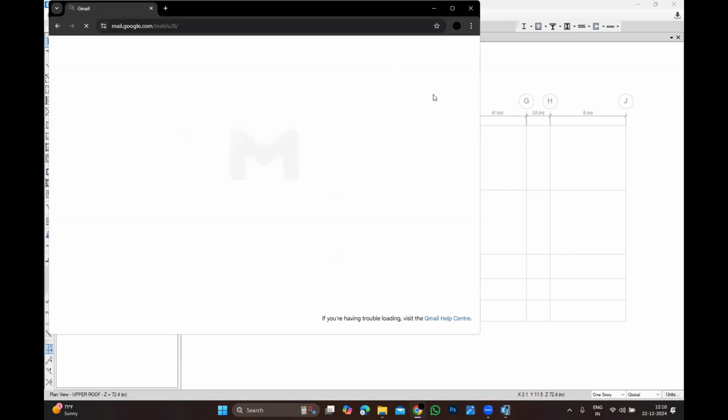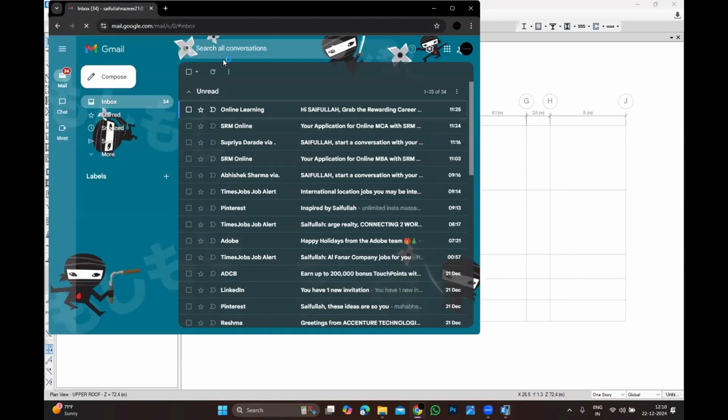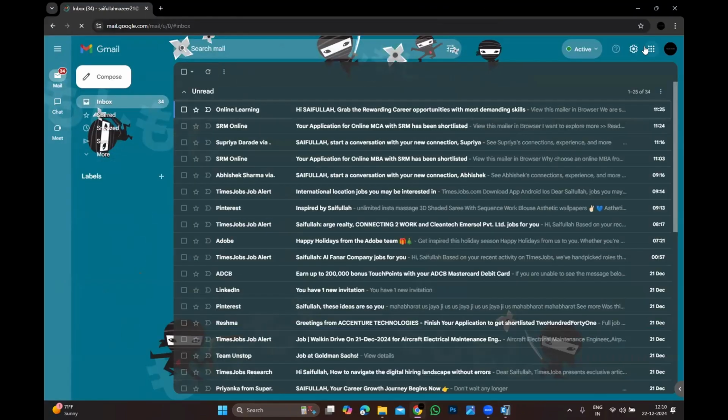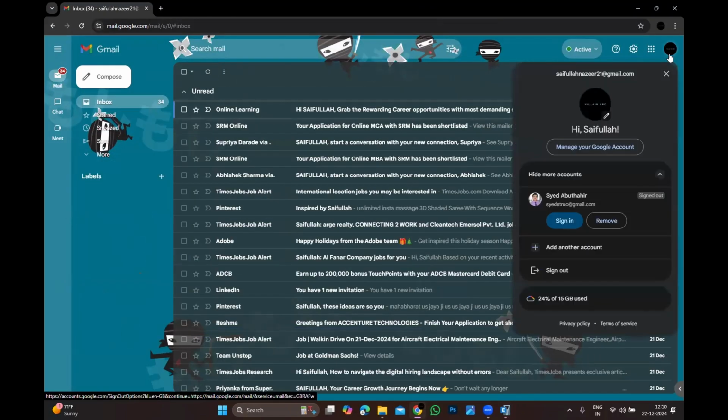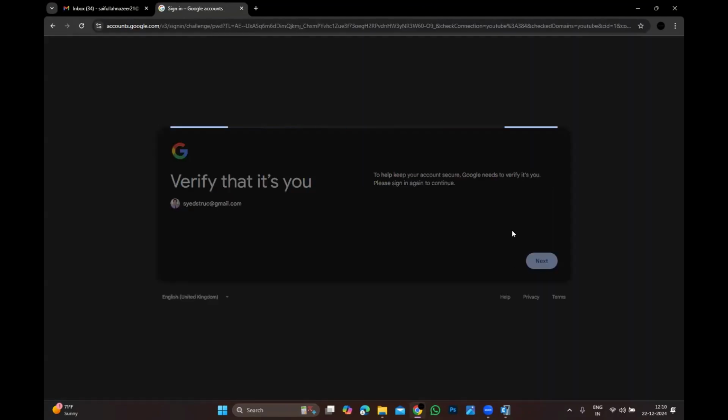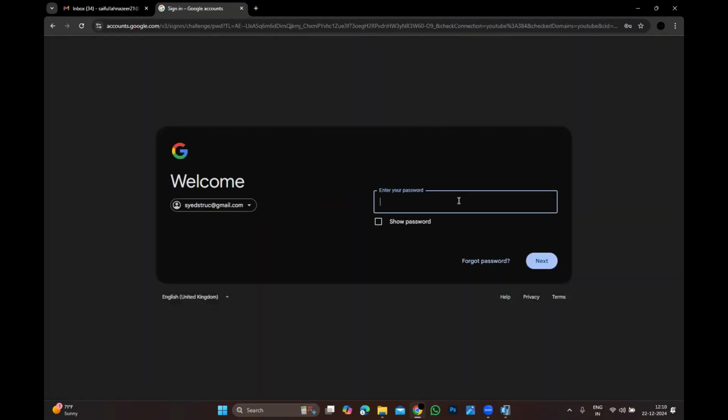SDL only, including combo roof, 3 kilonewton. Two. Actually, 1.5 is enough for accessible roof, but you can keep it 2. When you keep 1.5, actually DM will sometimes say no, increase it. See, people won't give gravity load much importance when it is 0.5, 1 and all, because your vertical element is so strong to take care of the gravity. The only problem is where you have lateral force, wind and seismic.